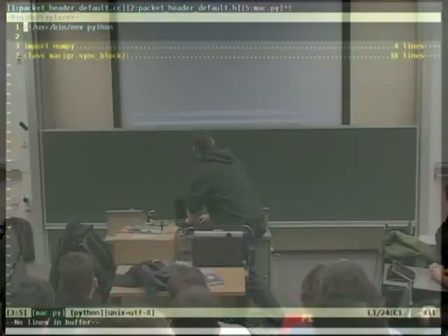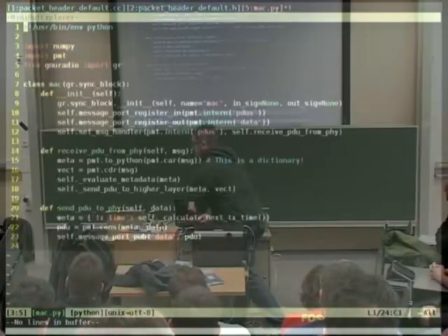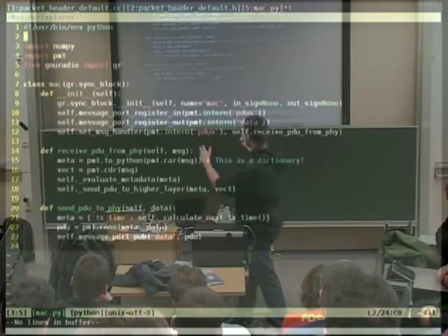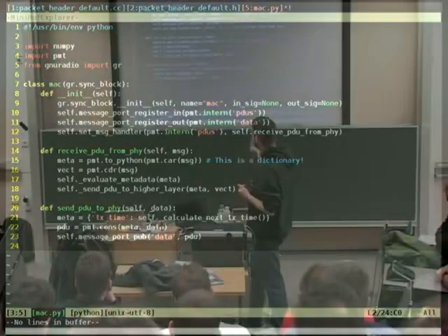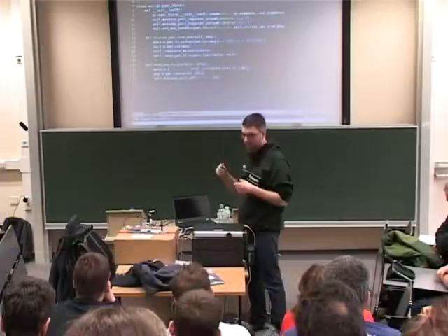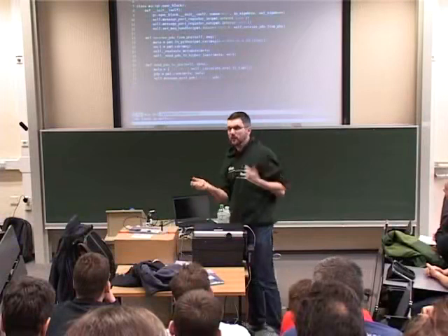So this is pseudocode. It won't actually do anything, but it's still valid Python code. I just ripped out everything that wouldn't get my point across. This is a GNU Radio block, and it has these ports where you can put in the asynchronous data, and it'll also come out. It's a block that talks to the file layer and to a layer above.